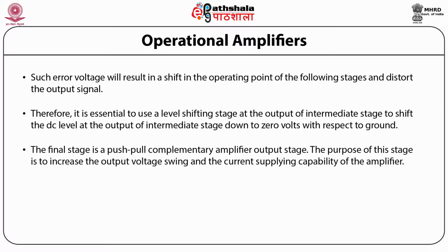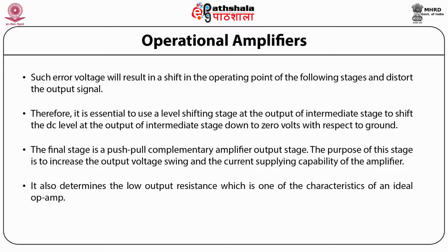The final stage is a push-pull complementary amplifier output stage. The purpose of this stage is to increase the output voltage swing and the current supplying capability of the amplifier. It also determines the low output resistance, which is one of the characteristics of an ideal op-amp.